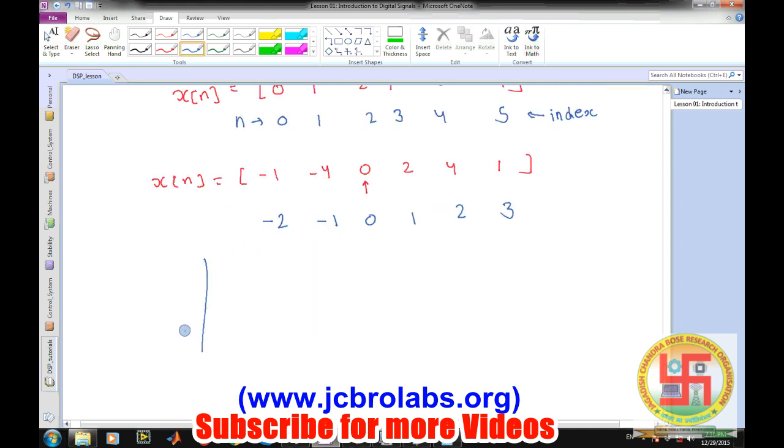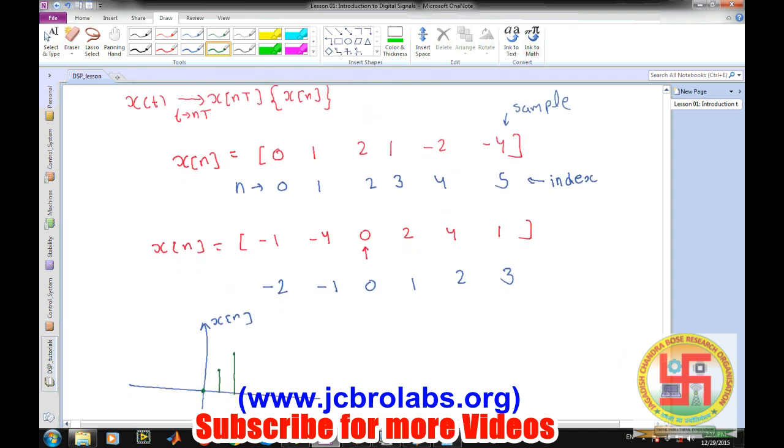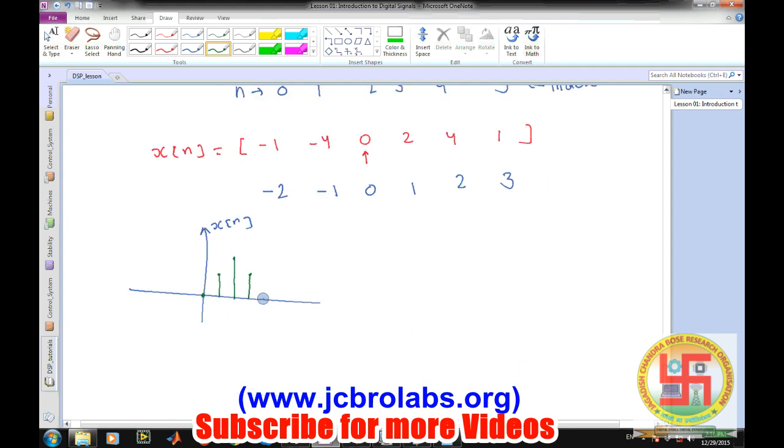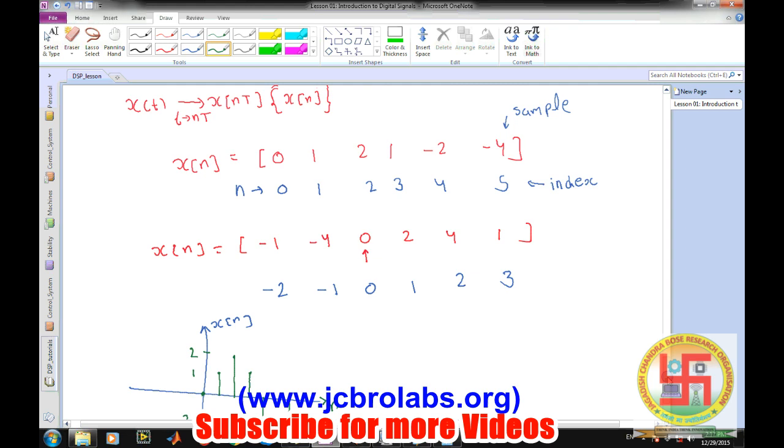In the graphical domain, we can also represent it like this. So this is x of n. It is 0 at 0. So let's say 0, it is 1. Then 2, the sequence was 1 again. Then minus 2, and then minus 4. So this is 1, this is 2, this is minus 2, and this is minus 4. Similarly, we can also plot such a graph for this x of n. So these are the representations of this digital sequence in the digital domain.